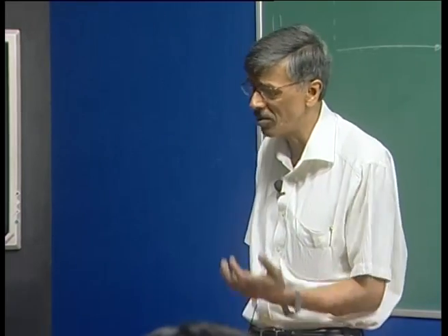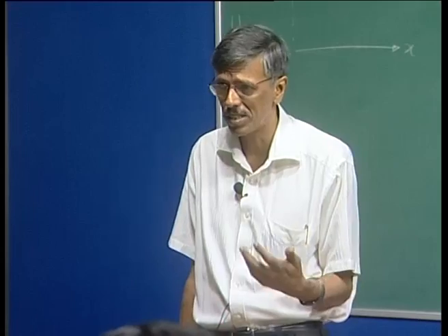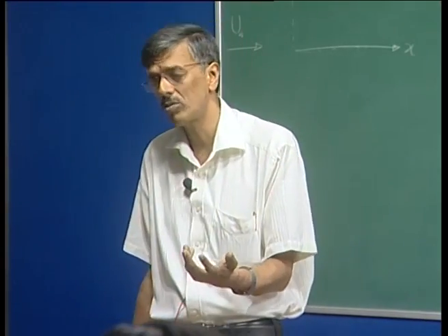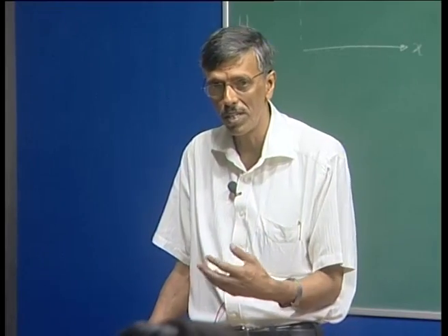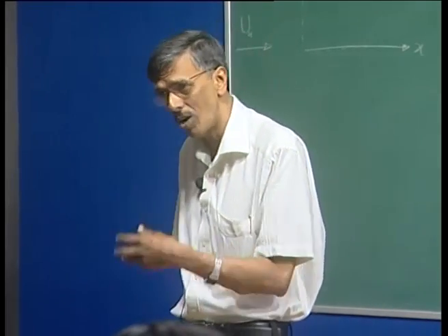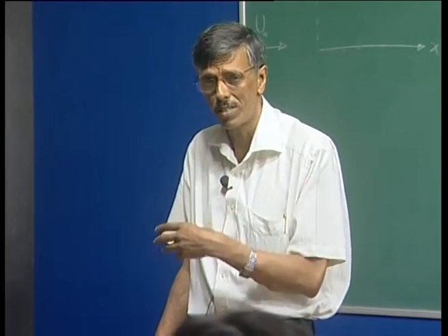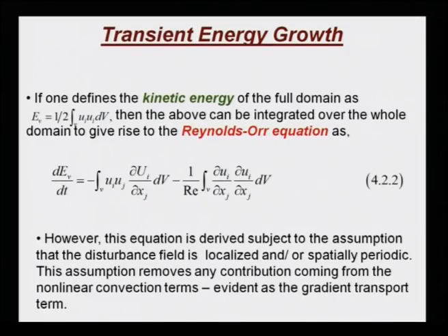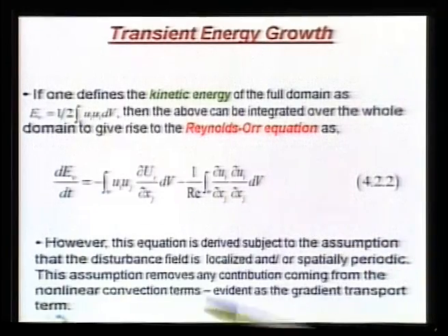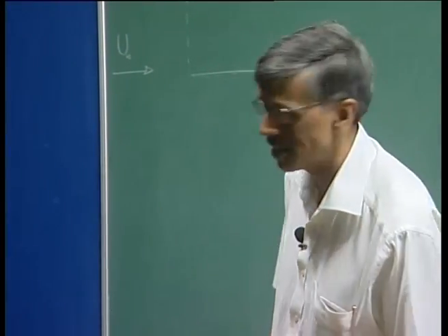And what we are noticing so far is that most of the time the nonlinear convection terms are important. Even if you start thinking of Rayleigh's equation, that was essentially the role of the nonlinear convection term, right. Then in the Sommerfeld equation also we looked at the nonlinear convection term, and how it exchanges energy with the viscous diffusion term, that thing came about. But in this equation, the Reynolds-Orr equation, you lose the nonlinear term altogether, right.